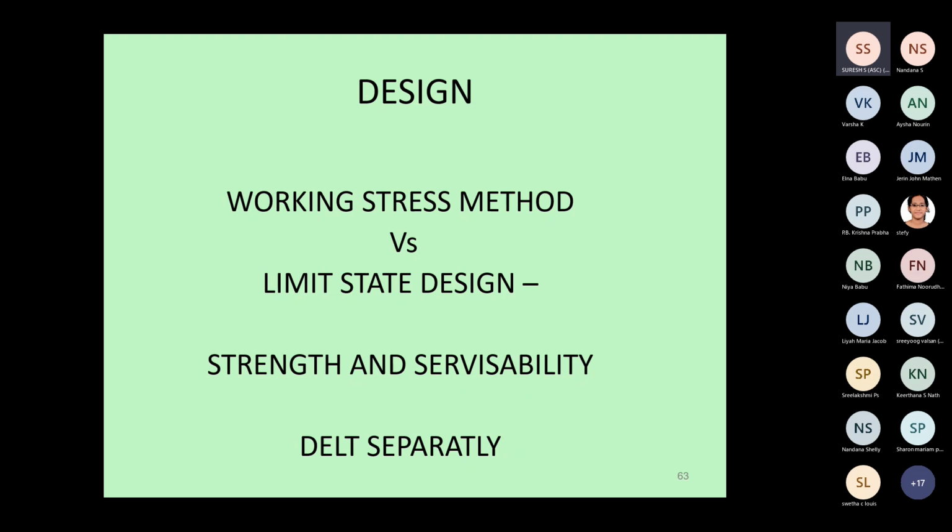Similarly, if you take Fe 500 TMT bars, which is the normal reinforcing steel all of you see anywhere in a site nowadays, the test should yield, if we conduct 100 tests on the same material, same material meaning samples from the same lot, 95% of the tests should have a value of 500 Newton per mm square or better.